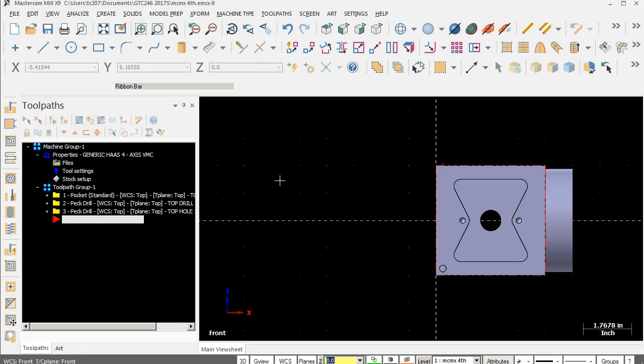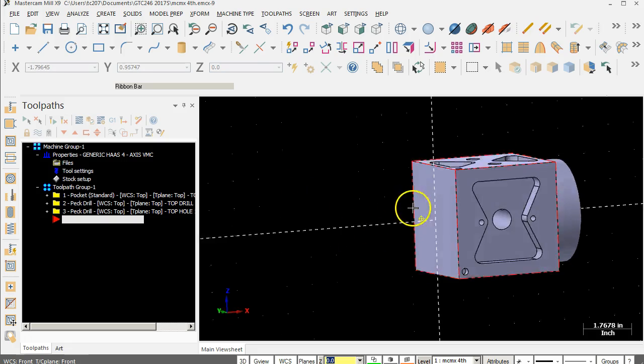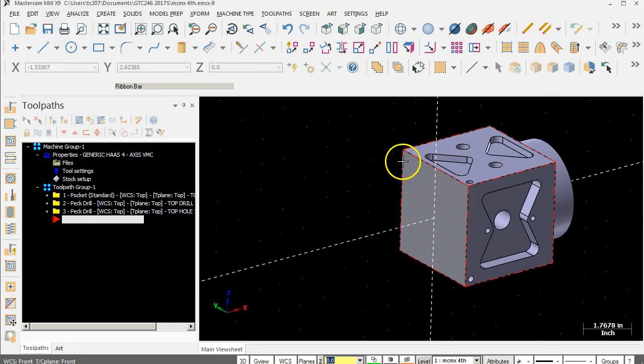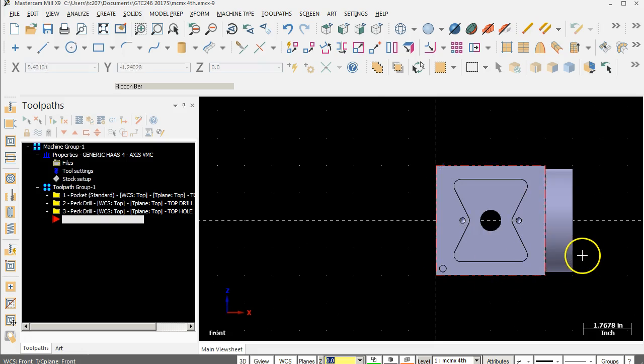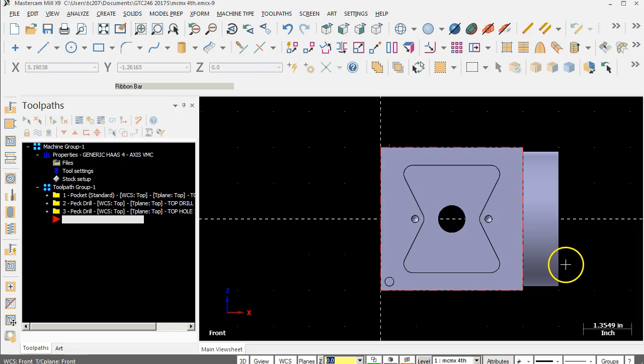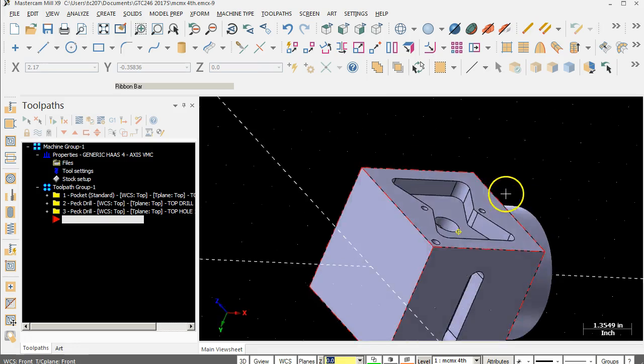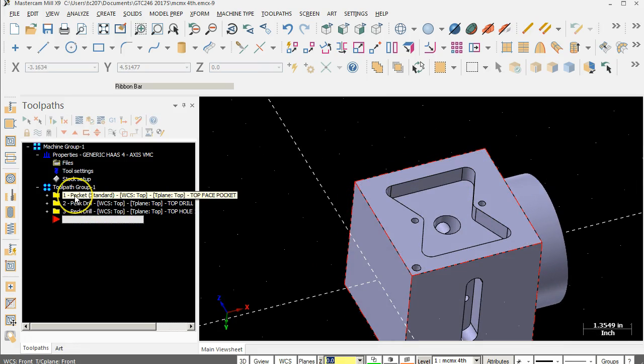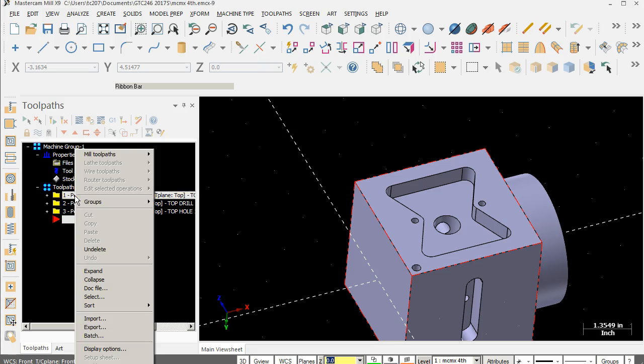So what we're going to see is when we go to what would be the back side, if I stayed in this top, I would still be looking at this face. And so when I'm making those selections, going to the current, in this case Alt-1, that puts me normal to that operation, and we can go ahead with it. All right, so I want another pocket, so let's go ahead and copy.